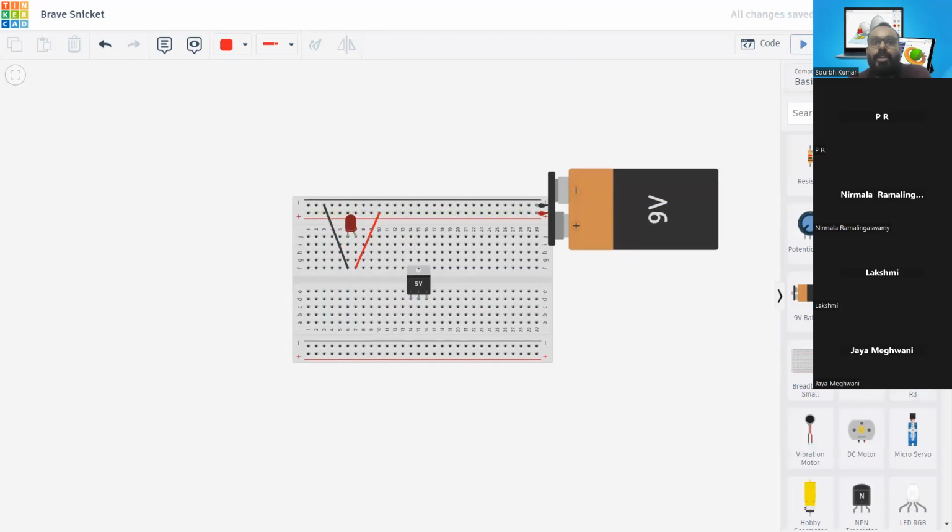And if I hit this simulation, then you can see what is happening. It says current through the LED is 915 milliampere, while absolute maximum is 20 milliampere. So now you do have a proper idea of what is happening in here, right? We are trying to overpower the LED with our voltage and current. So this is not advisable at all.